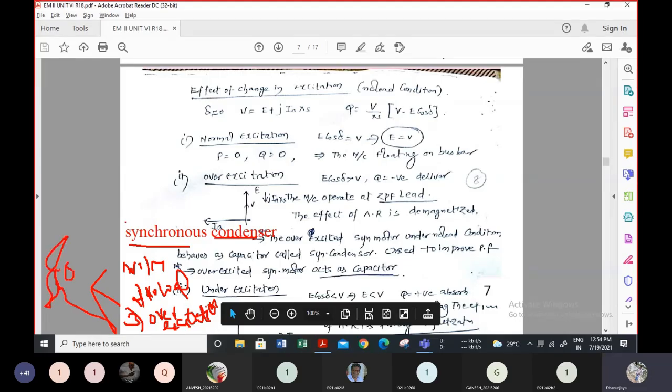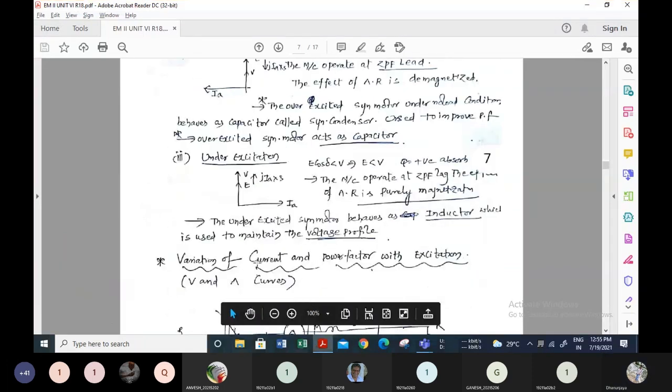With all these conditions, Q is positive. Reactive power, Q is negative. Sorry, I'm sorry, Q is negative, and it is delivering the reactive power. That's the reason in some situations, in summer times, when reactive power is less in the total system, these machines will be operated as synchronous motors under no load condition, so that they act like a capacitor. Hope it's clear.